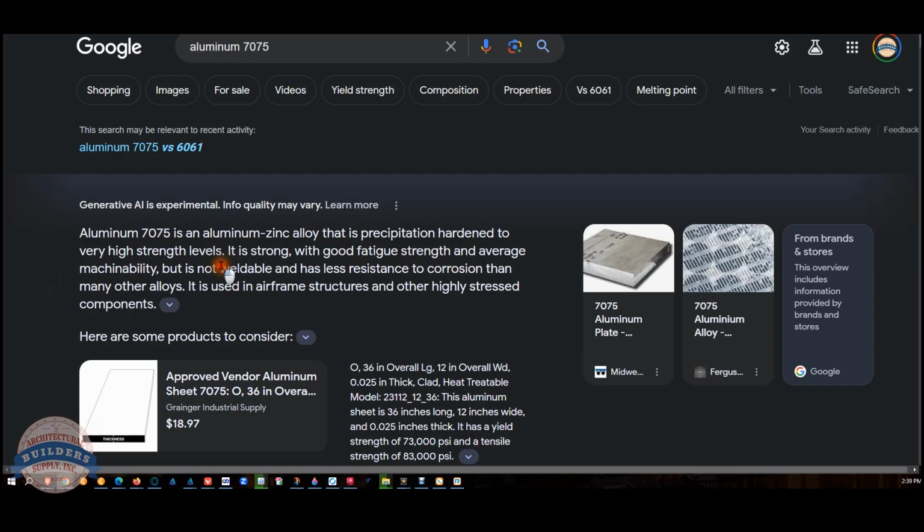I do want to be able to weld aluminum, even though I don't do it. I've not taught myself how to do it. I can weld steel, I can MIG weld, I can oxyacetylene weld, meaning I've done all of this. I just never learned how to TIG weld. If that comes up, then we'll look at it. So 7075 would not be an alloy that I would choose to use because it's harder to cut and I can't weld it. So 6061 is what we're going to use because it's known for machinability.